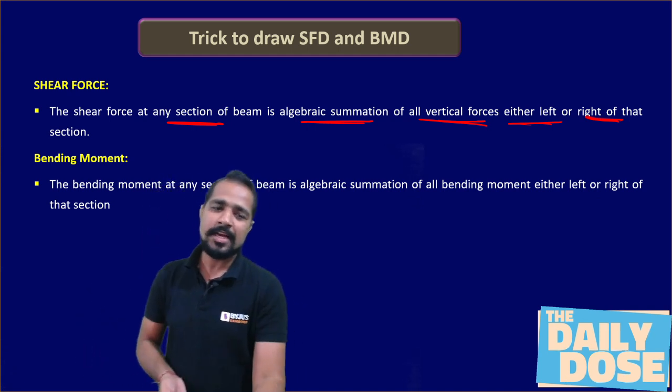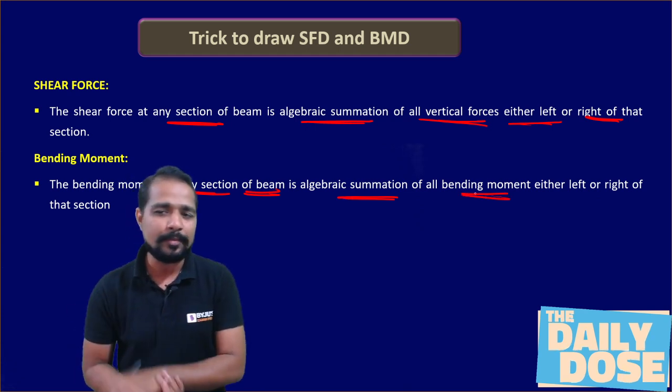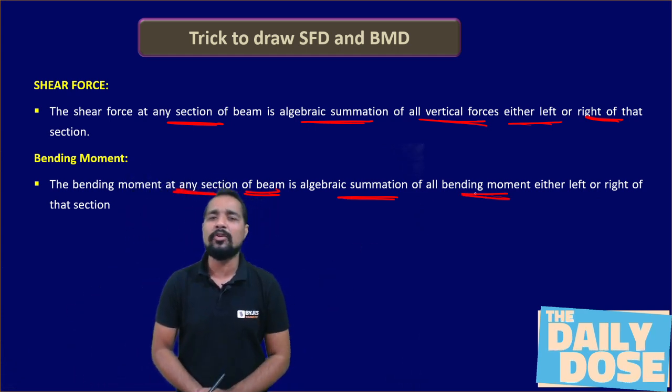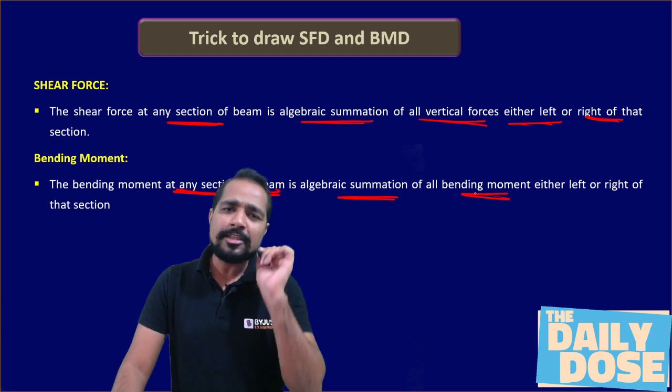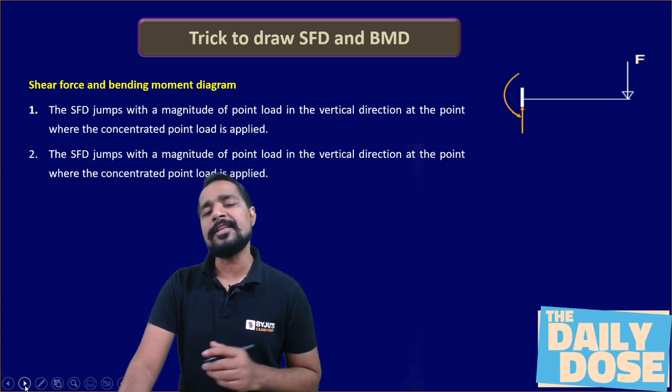force. Similarly, bending moment at any section will be the algebraic summation of all bending moment either left of that section or right of that section. Now let's follow some important steps to draw the SFD and BMD.